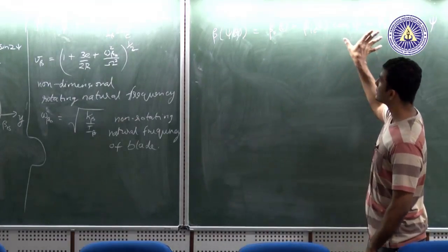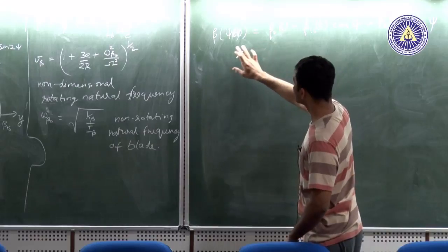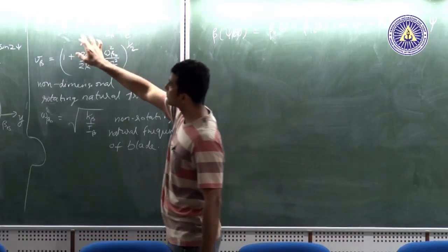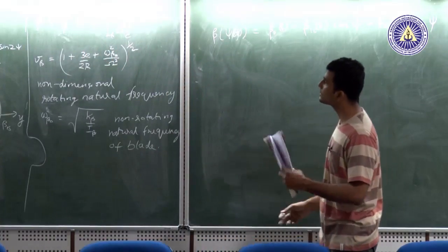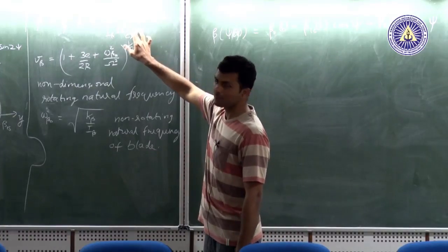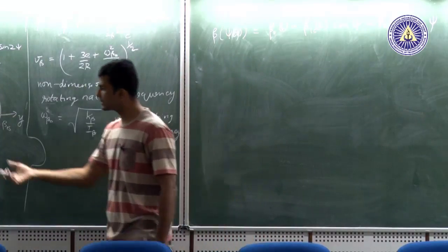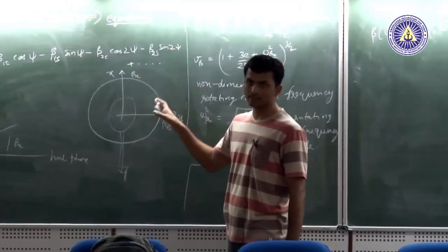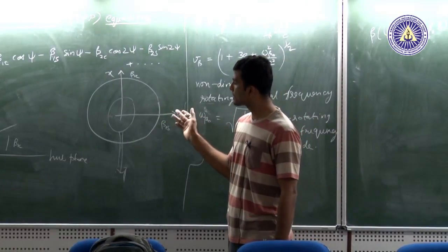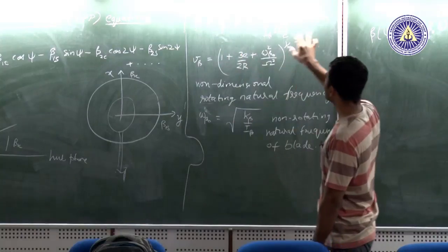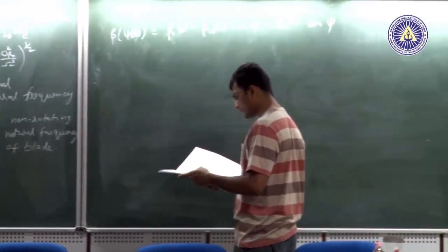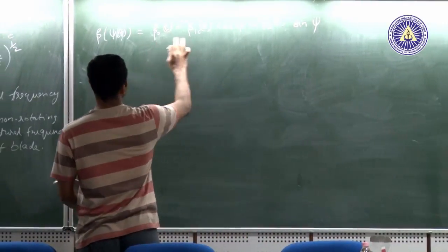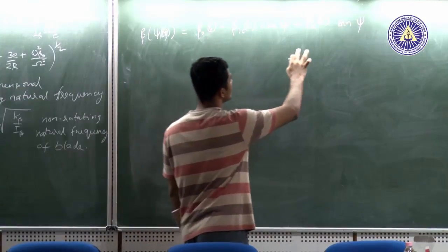So if you substitute this relation of beta into this equation, and of course you need to write your fz as a function of angular velocity of your fuselage and the flap angle and the rate of change of flap angle, and you expand all these things, then you will eventually get a second order equation in terms of these three, beta naught, beta 1 c, beta 1 s.